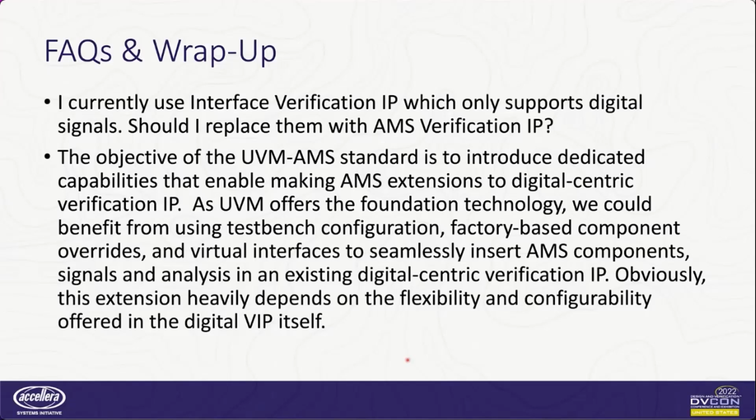If the standard has been updated and is now allowing the use of analog signals on the ports of that IP, then the UVM AMS standard will allow you to just pull the old digital VIP and put in the new mixed signal VIP, and it will drive the same ports with just different representations.